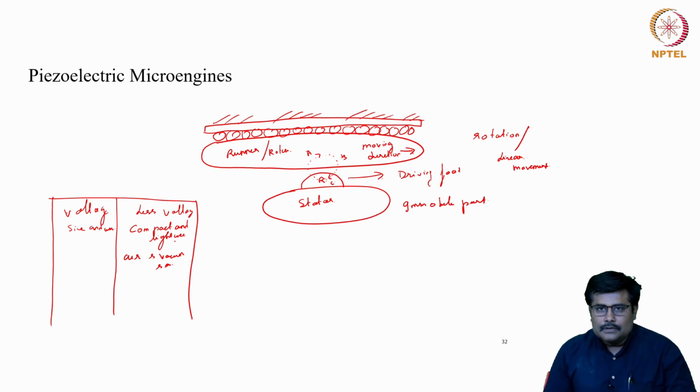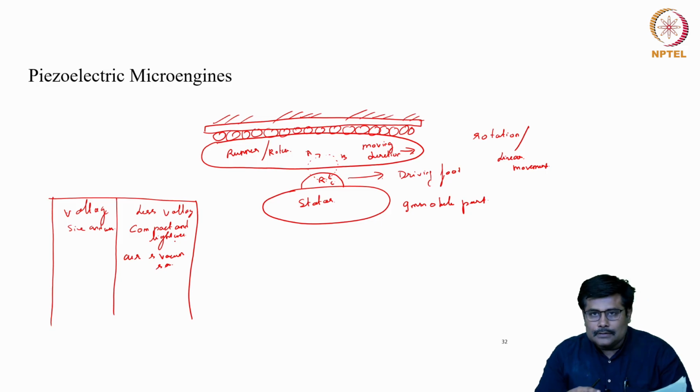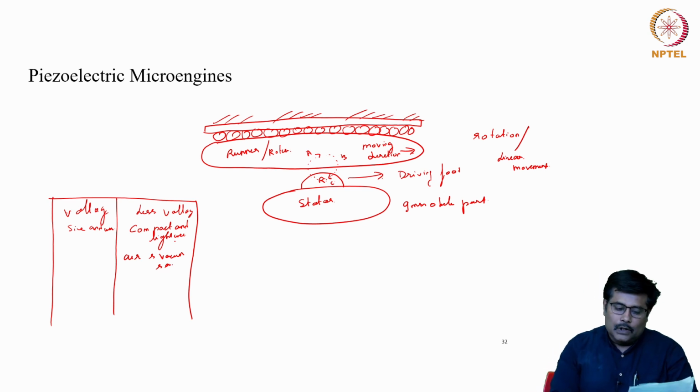However, from the disadvantage point of view, they usually generate small power with low efficiency, which involves a two-step energy conversion technique. Like in this particular case, there is a transformation of stator vibration into a macro one directional motion of the rotor via the friction between the rotor and the stator, which may cause energy losses.